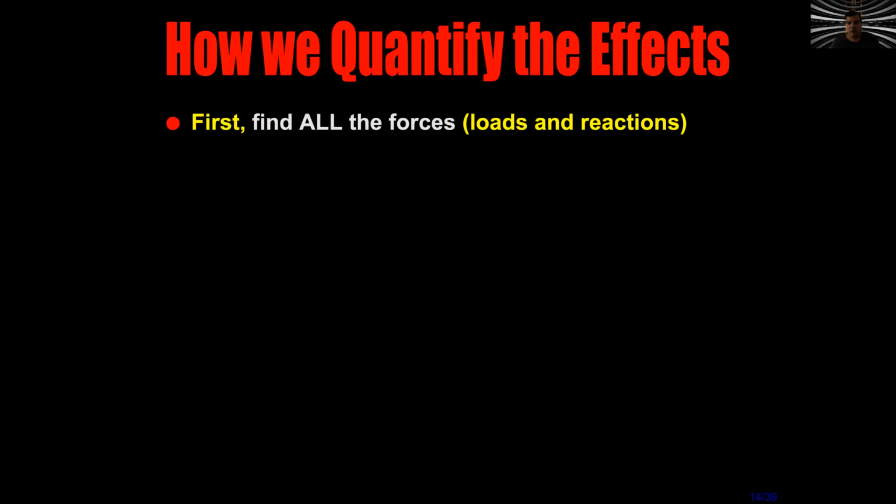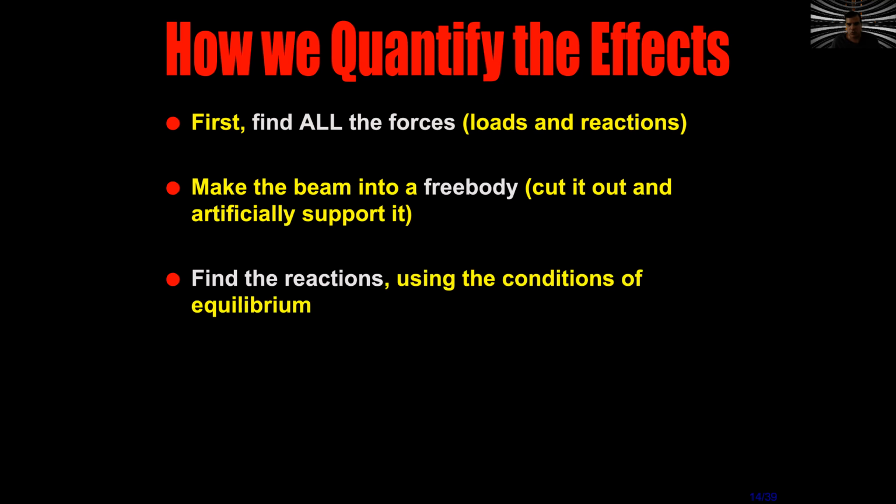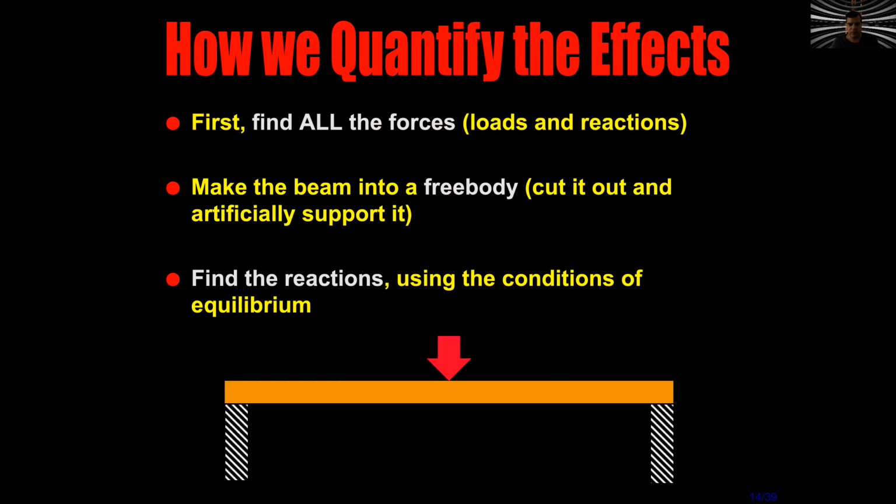Well, how do we quantify all those effects? We need to know all the forces, the loads and the reactions. We need to make the beam like a free body. We will cut out everything that is supporting this beam, and we will imagine how this beam is working. We will find the reactions using the conditions of equilibrium.